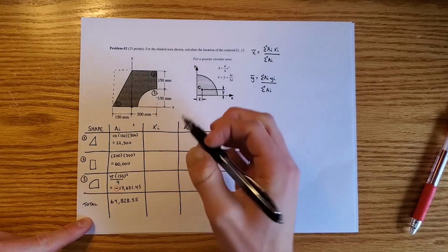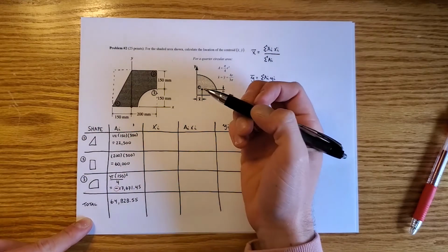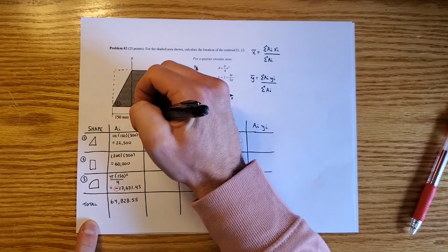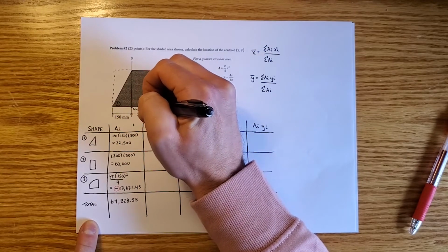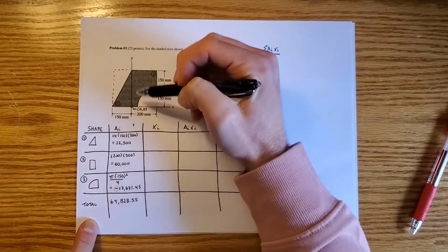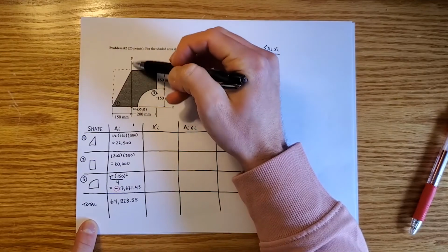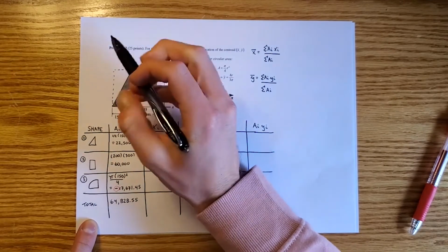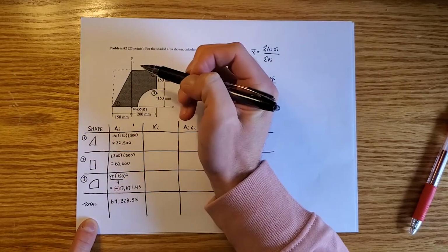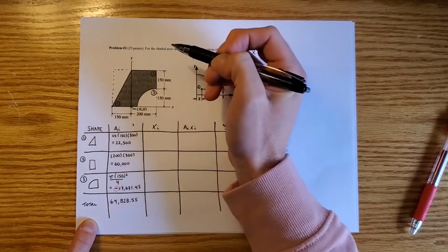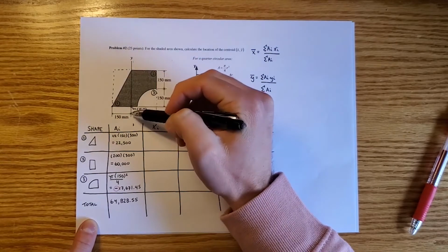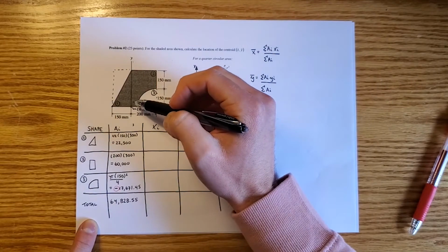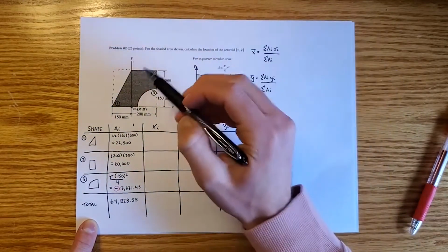millimeters squared. Now what I have to do is solve for xi. To solve for xi, I'm going to be using this point right here as our datum, because you can see our y-axis goes through the shape and our x-axis is down here. Now, in theory, you can choose any datum point you want. You could have chosen down here, or up here, but usually you want to choose the intersection of the xy axis because most exam questions will ask you to solve for the centroid location from